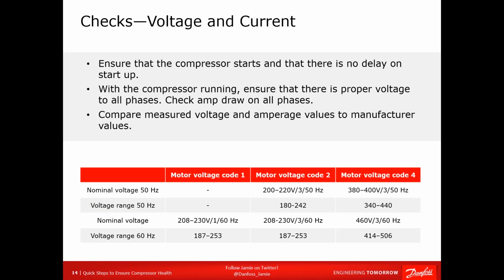If the main supply is already tired and overloaded, and you're putting another few kilowatts on it, you might see a brownout condition localized in your area. You might see a drop in voltage, and this is going to drive your current way up. This has to be addressed. Otherwise, that compressor you just put in isn't going to last.